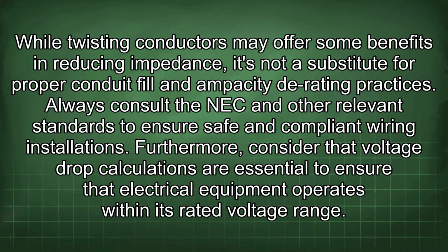While twisting conductors may offer some benefits in reducing impedance, it's not a substitute for proper conduit fill and ampacity derating practices. Always consult the NEC and other relevant standards to ensure safe and compliant wiring installations.